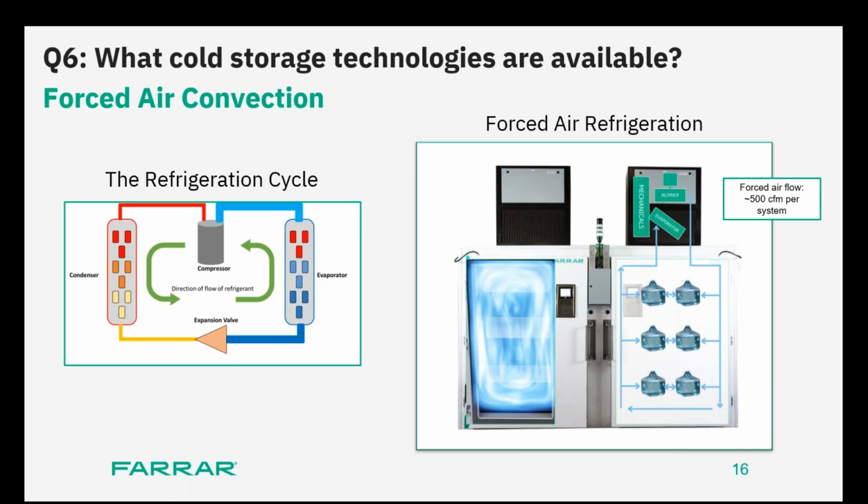So the first thing I would like to point out, and this would be the first aspect, right? If you remember the design with the standard ULT, the evaporator coil wrapped around the entire chamber, right? And that's how it worked. As opposed to that, if you look at the schematic here, the evaporator is actually sitting on top as a modular unit with a ULC. In other words, the chamber is actually separate from this, right? And there's a reason behind it, and we'll talk about this, right? In this case, all four components of the refrigeration cycle are housed together, and it's a modular unit sitting on top. So what are the advantages of having this design?